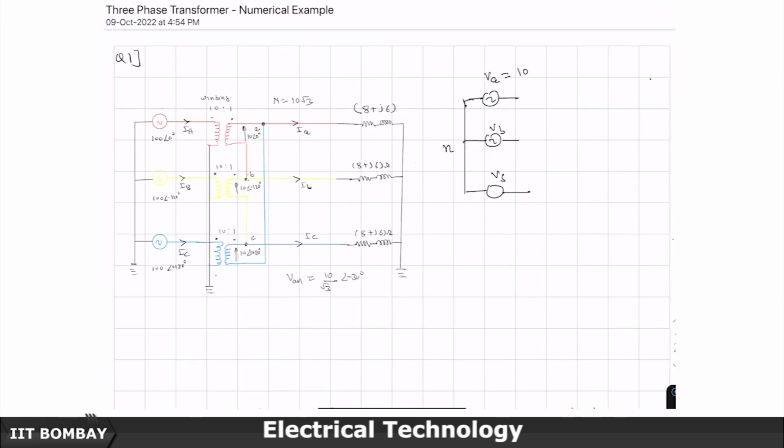So the value, and you remember capital N is 10 √3. So therefore the voltage we are here is going to be, either you can think of it as 100 by capital N, which is 100 by 10 √3, which is same as 10 by √3, and then we have shown that this star to neutral leads this star to neutral by 30 degrees.